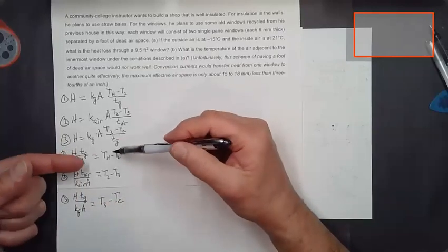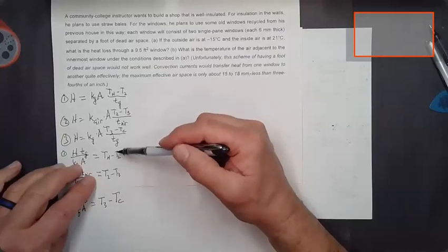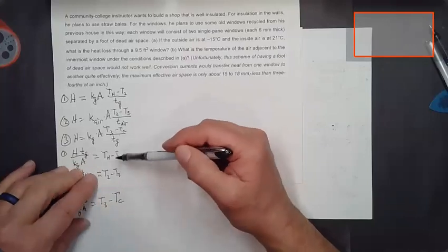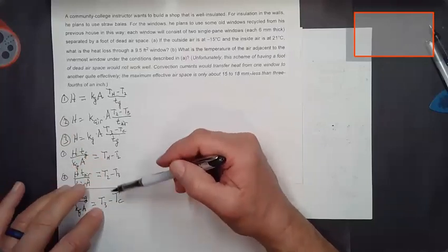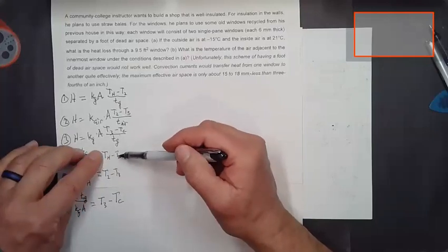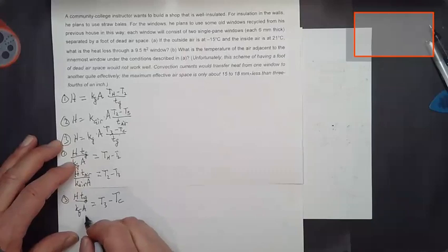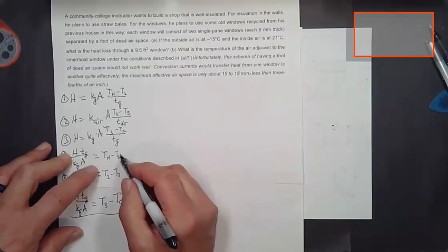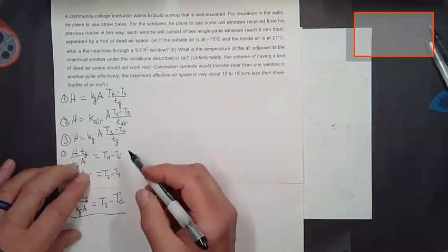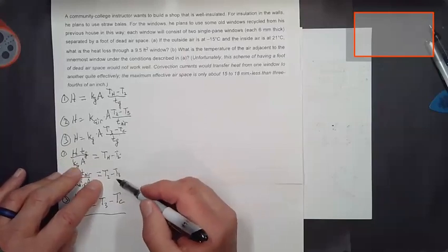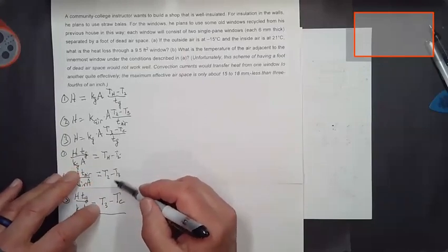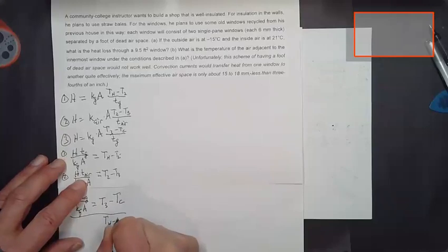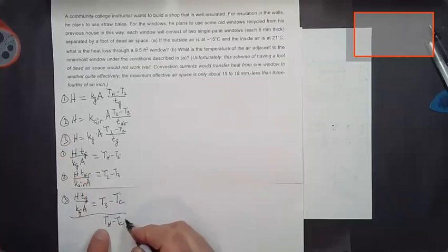And as we did yesterday, if you look down the right side of this equation, TH minus T2, T2 minus T3, T3 minus TC, I can add these three together and add these three together. And what'll happen on this right side is that the T2s will cancel out because I've got a minus and a plus. The T3s will also cancel out, because I've got a minus T3 and a plus T3, and I'll just end up with TH minus TC, both of which are numbers that I know.